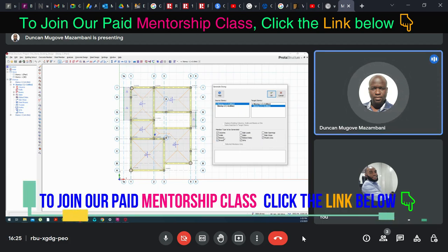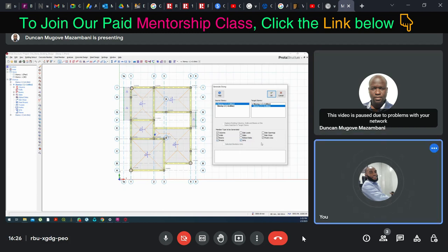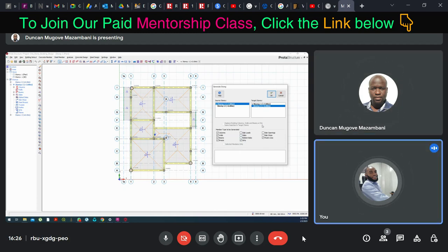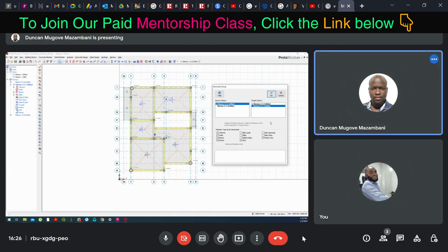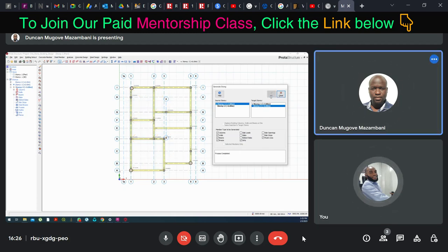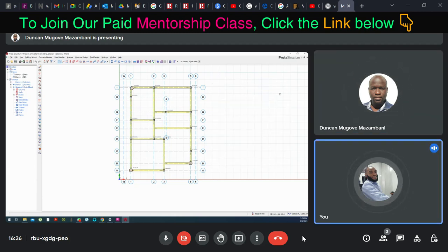Only the slabs are removed. Just the slab, only the slabs, leave the rest. And the gates, you can leave that. That's for steel if you're doing it for steel. So only take off the slab. So click on OK right now. Okay, that's fine. And then click on Process completed, close. Now check your 3D view and see what we have done so far.